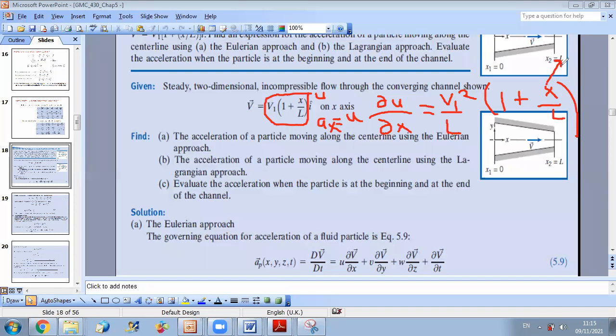And this type of acceleration is called convective acceleration. This is related to location. So the particle is accelerating with location. In the flow field domain, I have acceleration with position, not with time. Because if I observe one fixed location, the velocity is not changing. So if I consider any point and I observe it at any time, I will get the same velocity. This is why I don't have here a local acceleration. I just have a convective acceleration related to change in x position.